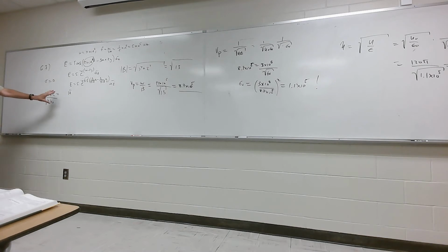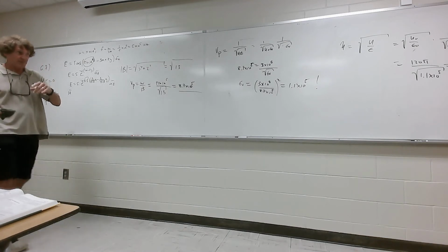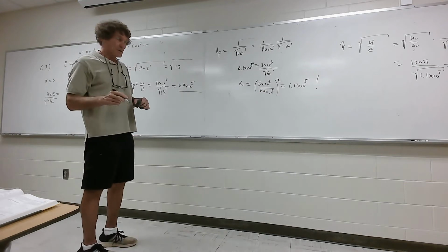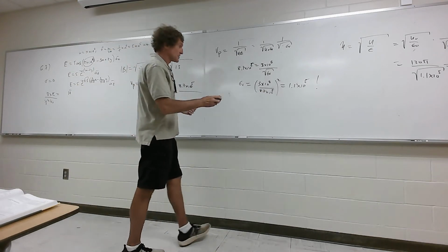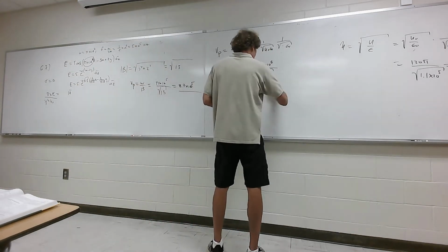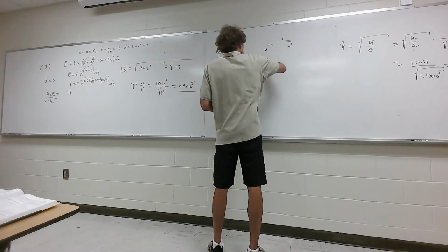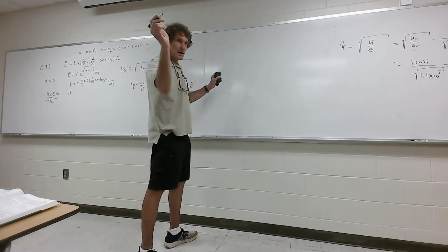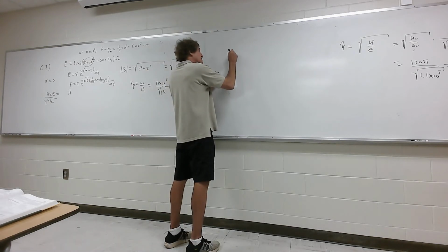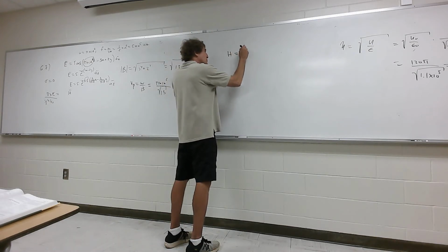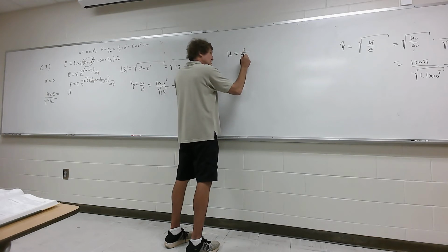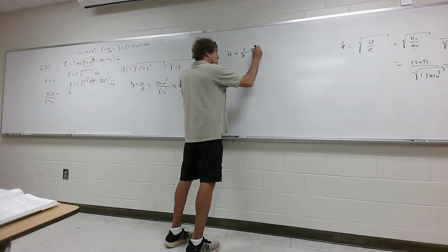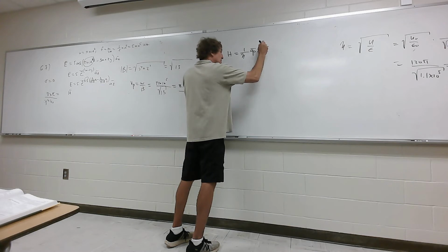This will not get you the same value I'm about to show you. This is the right value. If that's the impedance, then the actual value of the H field, how do we get it? Remember, this is a plane wave propagation. Right, we use that trick. H is equal to 1 over eta, and it's lossless, times the unit vector in the direction of propagation crossed into the E field.